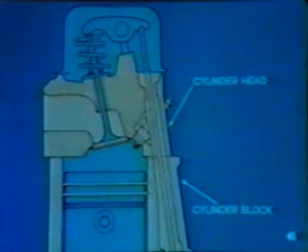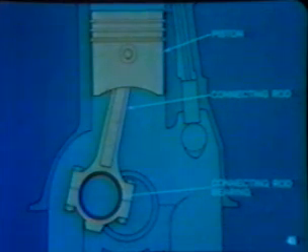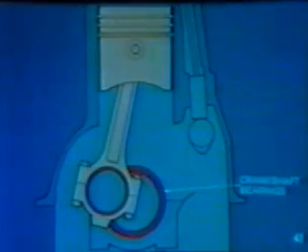Above the cylinder block is a cylinder head, which forms a roof for the combustion chambers. The pistons then are fitted into the cylinders as floors for the combustion chambers. They are linked to the crankshaft by connecting rods and bearings. The crankshaft is mounted in bearings at the bottom of the cylinders and is used to receive the engine's power on one stroke and push the pistons back and forth on the other 3 strokes.